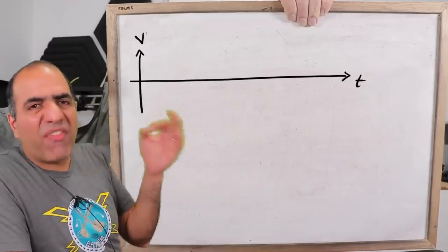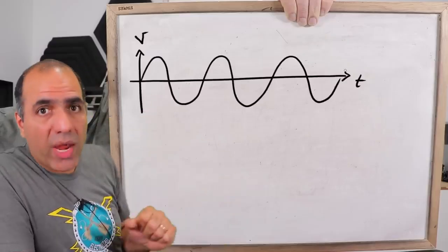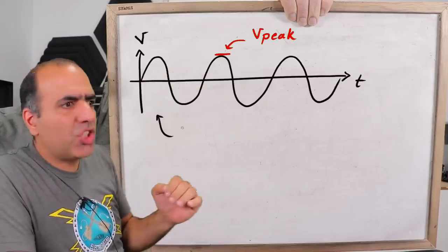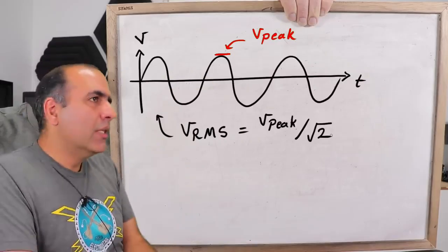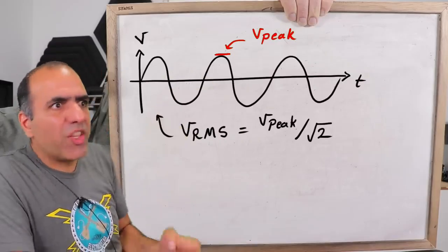The brightness is around the same, if not worse. And the resistor is smoking. Why is it not brighter? See, the RMS or effective voltage for a full sine wave is its peak voltage divided by square root of 2. But we have an LED diode which